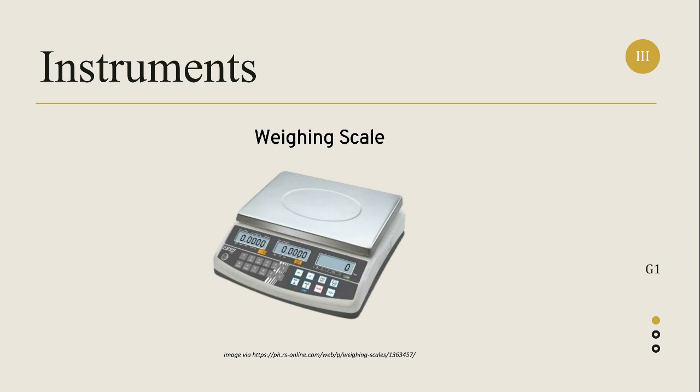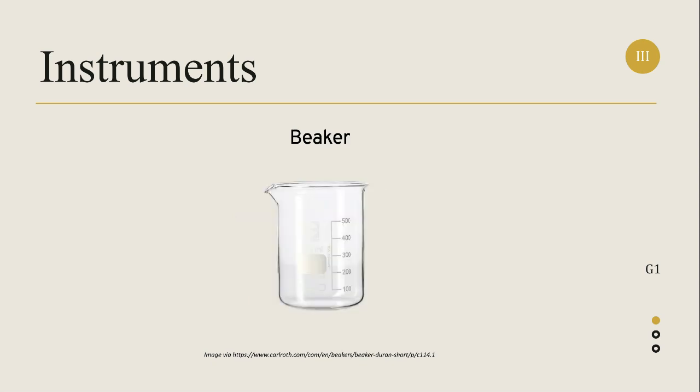In the standard test method for compressive strength of hydraulic cement mortars, here are the instruments used. First is the weighing devices. The weighing device shall be evaluated for precision and accuracy at a total load of 2,000 grams and shall conform to the requirements of specification C1005. Next is the glass graduates, preferably large enough to measure the mixing water in a single operation. These graduates shall be subdivided to at least 5 ml, except that the graduation lines may be omitted for the lowest 10 ml for a 250 ml graduate and for the lowest 25 ml of a 500 ml graduate.